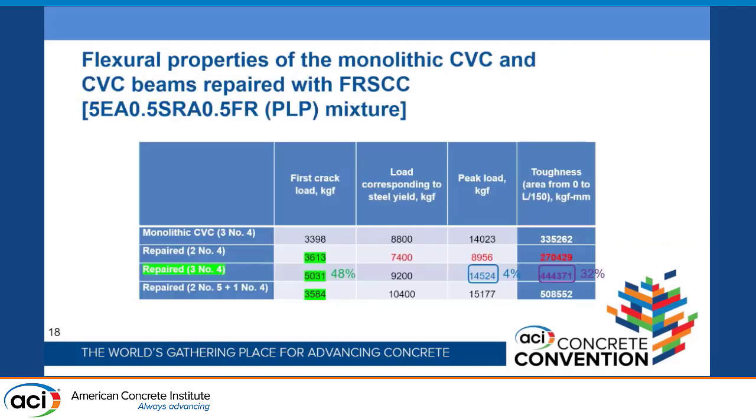Here is more detail about that flexural test: 48% higher first crack load, 4% higher peak load, and 32% higher toughness.